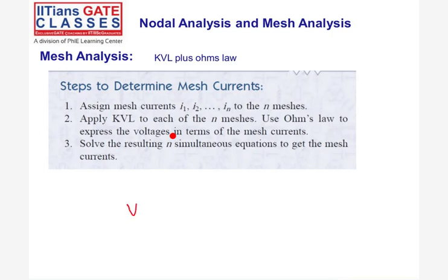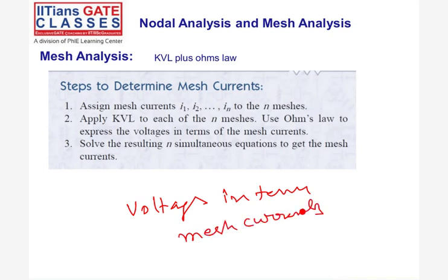Again, similarly, why is it named super? Because if you have a voltage source, you can't write a node equation here. Why? Let me explain this. So if I have a node here, VA, I can write the current here as (VA minus 0) by R2. Here also I can write (VA minus some V1) by R1.